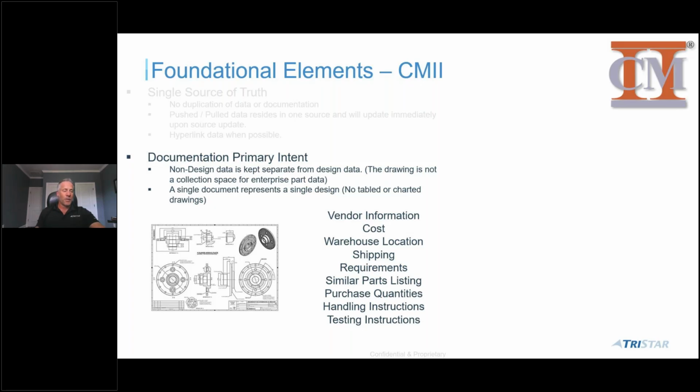Now, when you move to the WT part, there are good best practices around what should and shouldn't be on the WT part as well. And so for those of you that are admins in your Windchill system, it's critical that you start developing a good, detailed data model for what Windchill really looks like, and that runs all the way down to the attribution on your WT parts, on your CAD, on documentation in Windchill, whatever it may be. It's very critical that you develop that and have everybody in your organization understand what your detailed data model looks like.